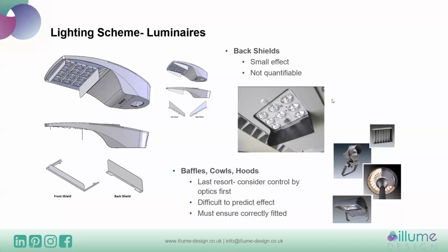And the same with baffles, cowls and hoods. Really, they should be considered as a last resort. They are difficult to predict as well, the effect from those. And we need to ensure that they're actually fitted as well. So where you are using those kinds of measures, we need to ensure that a post-installation check is done to ensure that they've actually been fitted and are doing the job that they're supposed to do.